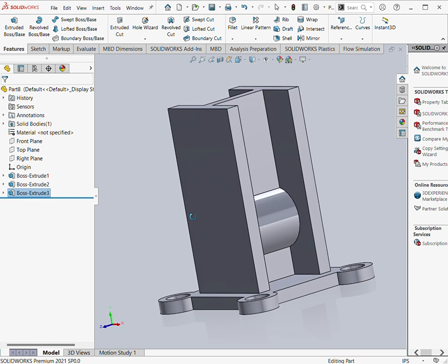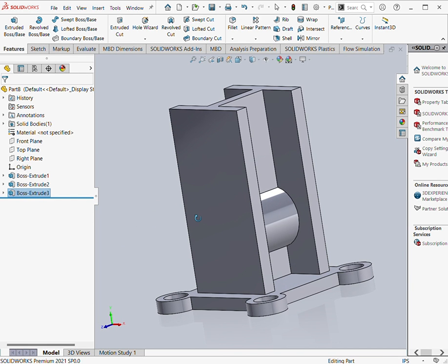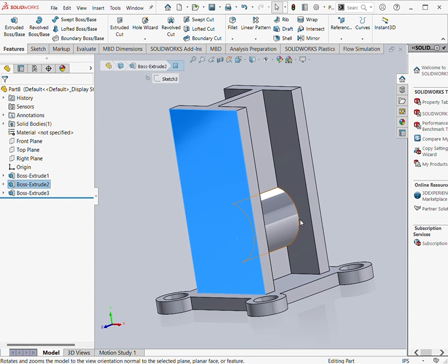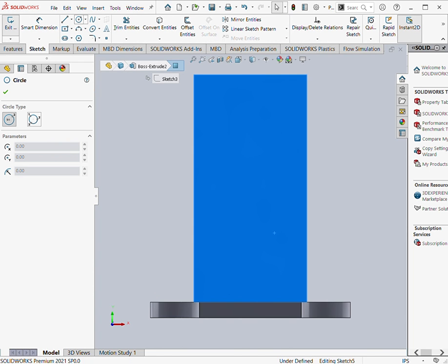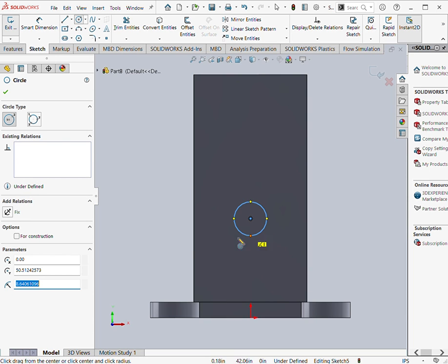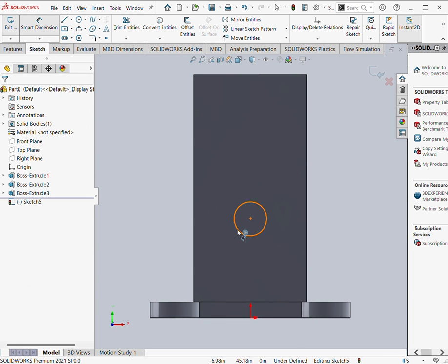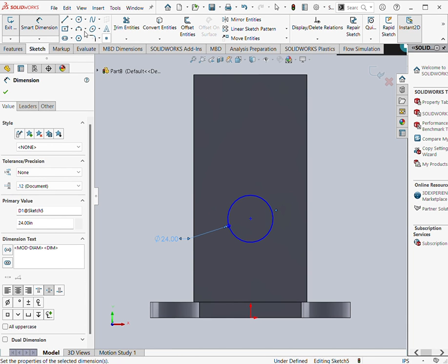This one. So in this way you have a circular cylinder to make cutouts. First we need a material, later on we will make cutouts. Now you need to make these variable cutouts. First cutout is sketch. This cutout is of radius 12. Again you will say radius 12 means dia 24.